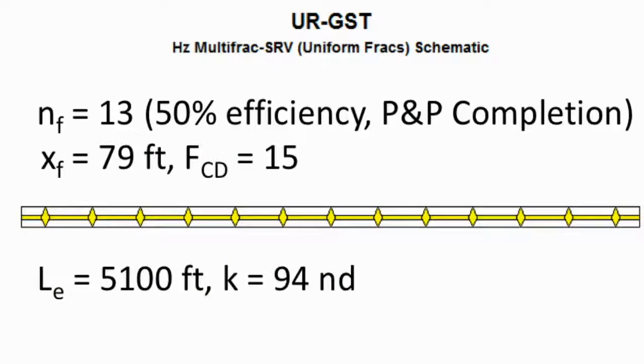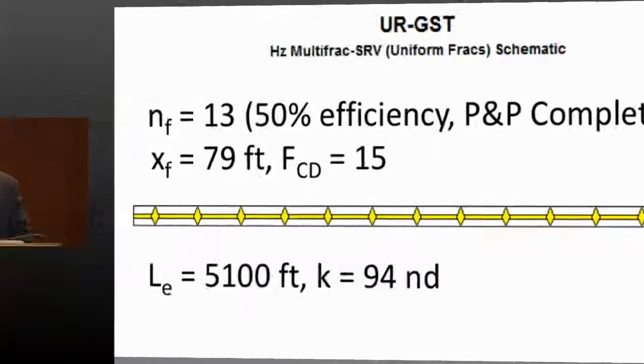And that cartoon can be captured in the bottom right-hand corner there, which is again a very overly simplified understanding of looking at the completion and seeing that the fracs are far apart because of inefficiencies in the stimulation, and of course the onset of pseudo-radial flow around those fracture faces is inevitable with that type of configuration.